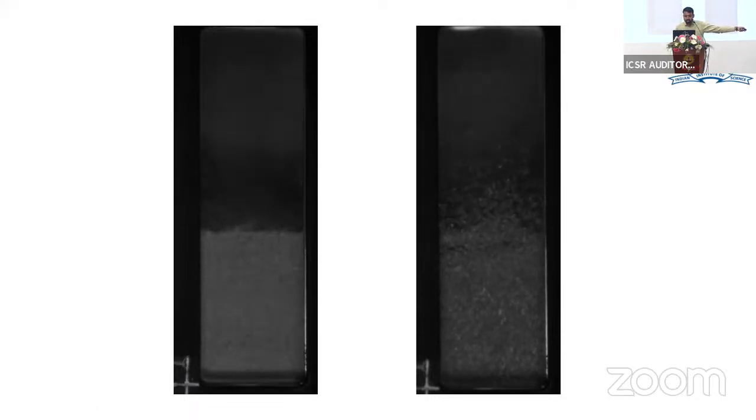The reason, we can say, is that the glass bead is made of quartz, and we know that collisions between quartz particles are very near to elastic collision. So we think that due to this elastic collision, the intensity of the blast wave is not decreasing very fast in the granular media when it is glass bead, but in the case of sand, it is decaying very fast. We can also see that the glass beads that moved ahead have gained very much height, so energy is constant for those cases.